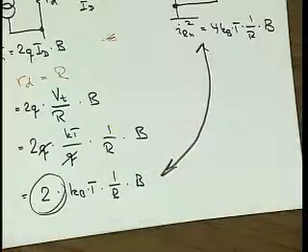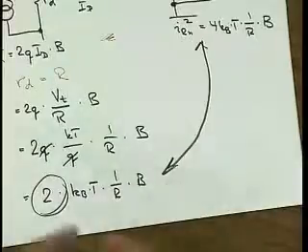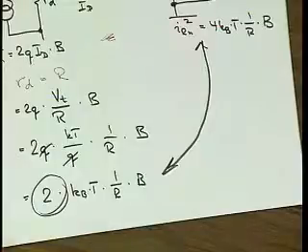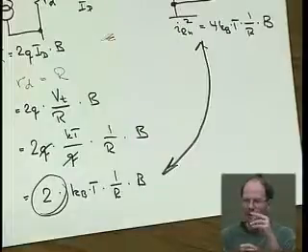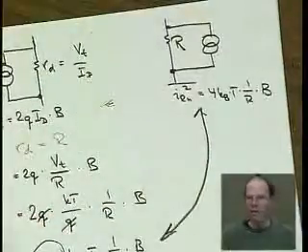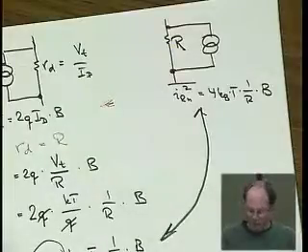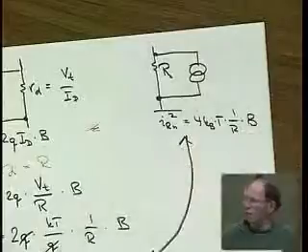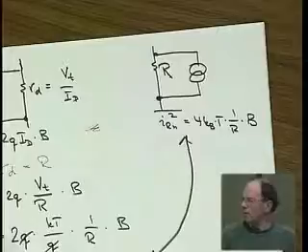So why does a diode produce more noise? Well, I went to ask the physicists, and they had a very wonderful explanation. They said, oh, it's not in thermal equilibrium. Now, whatever this means, apparently, if I have a diode and I run current through it to make up my resistor RD, then that thing is not in thermal equilibrium because I force this current through it. And then this whole 4kT noise equation doesn't apply anymore because I'm pumping power or current into the thing.